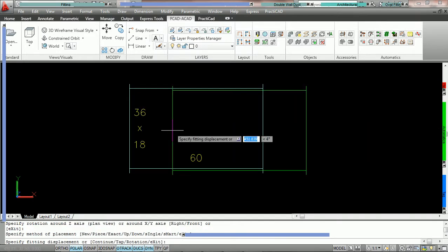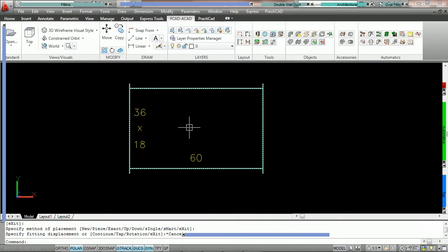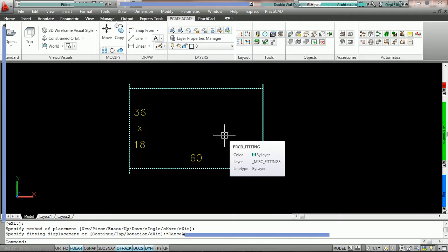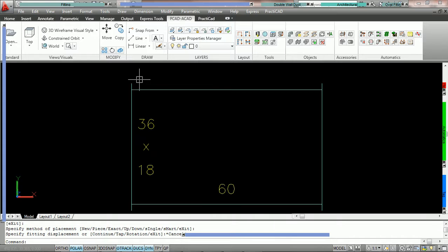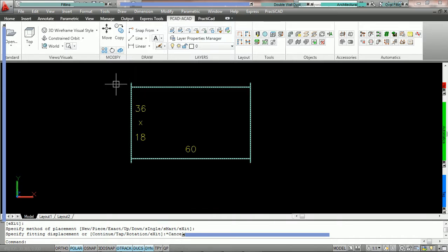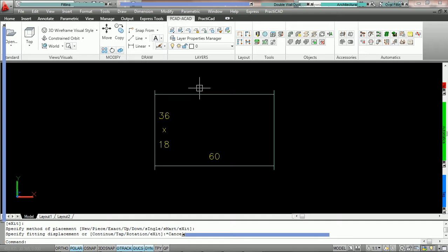So here what we do is we place the duct on the drawing. You can see that it's 60 inches from end to end because connector size is 1.5 inches and connector grown is 1.5 inches. So since they're the same, we don't lose material. But because we've added an accessory, we now get a 2-inch flange in our preview. This 2-inch flange can be used for collision detection and for BIM modeling. So for some connections where they have accessory flanges that are added, you could design these accessories in the connector accessories option, and then you could select them for particular connectors.